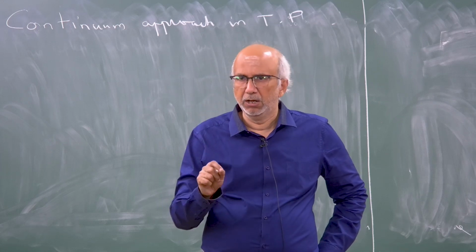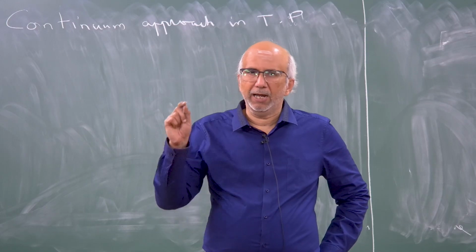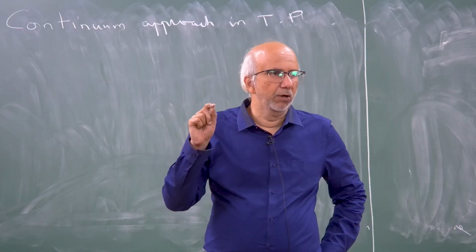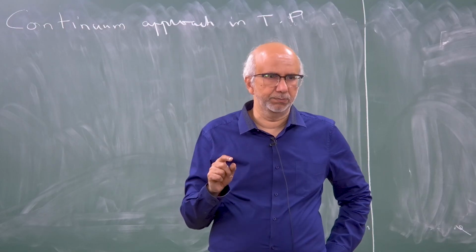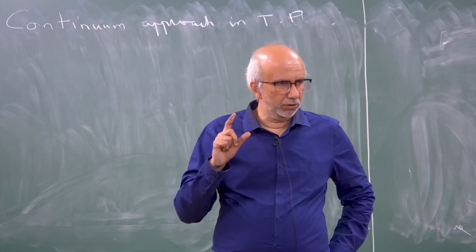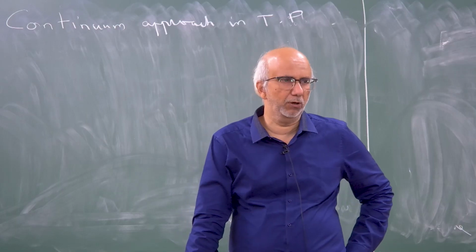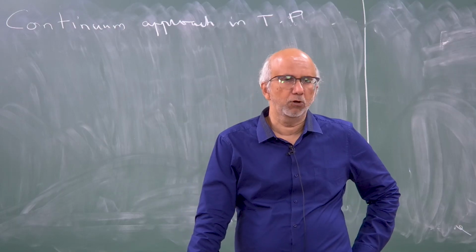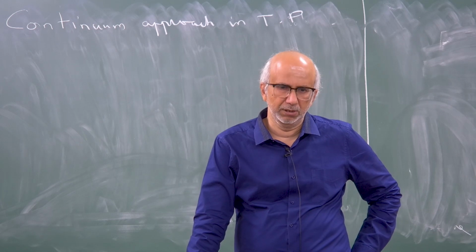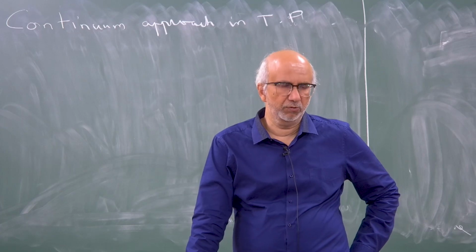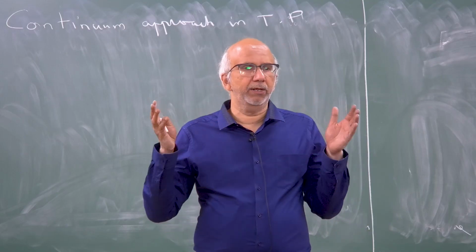When I say velocity, I am not talking about velocity of the molecule. What I am going to be finding is the average velocity of a bunch of molecules, okay, and the velocity that I am talking about is the velocity of the bunch of molecules which are occupying a particular point or a particular position, okay. I need to choose the size of this collection over which I am doing the averaging to be not too big, not too small.